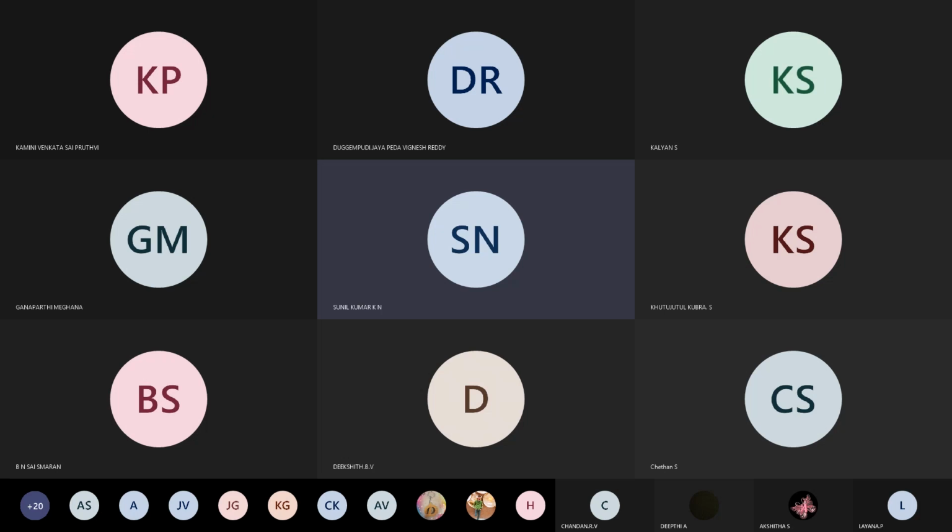So this is the ID signal current, and this is nothing but signal gate to source voltage. So small signal gate to source voltage, and this point and this point. So this is nothing but a VGS point, and this point is nothing but a VT point. So the difference between these two, VGS minus VT, this point is called the overdrive voltage. So you have to note all the important parameters with respect to the MOSFET, and this is nothing but overdrive voltage, and this is nothing but a quiescent point, and at that point what is the gate to source voltage, and at this point what is the drain current, and you're going to see.